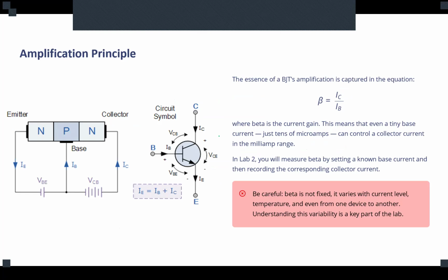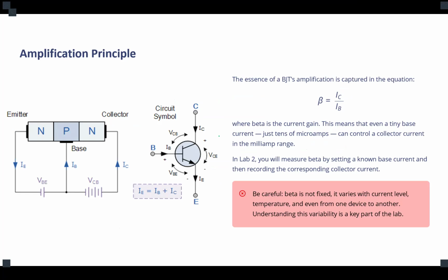Now, I want you to be careful about one thing. When you want to calculate the parameters and design your circuit, unlike MOSFETs and any type of FET, the currents between collector and emitter are not equal to each other. In a MOSFET, the gate was isolated from the PN junction, so it only applied voltage, and there is no injection of current from the gate.